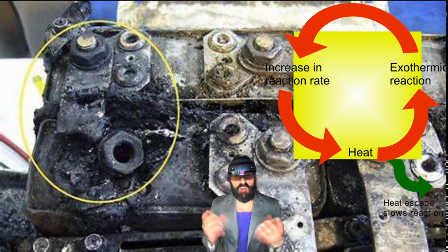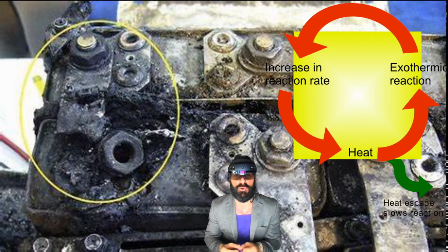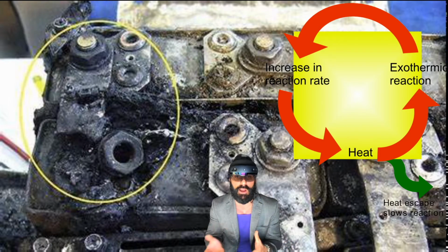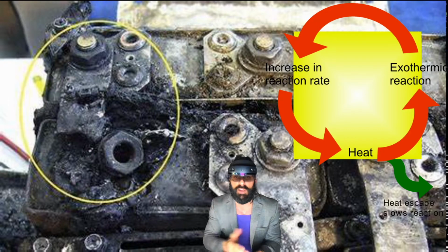Thermal runaway: understanding the fundamentals of this catastrophically dangerous situation, as it relates to electrochemical generating devices, is very important. So let's look at this really quick, and then I'll jump back into a few other components of review that I want to kind of dial in. But let's look at thermal runaway. Now, this is going to occur when a cell or an area within the cell has an elevated temperature due to a thermal failure, a mechanical failure, an external or an internal short circuit, a ground fault, or electrochemical abuse, hitting it cyclically thousands of times, or very deep depths of discharge.